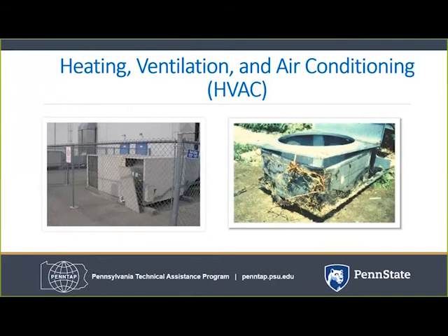There are several maintenance activities for your HVAC system that can save energy and money. First, check filters every 3 months and replace them if necessary. Tune up your HVAC equipment yearly. Look for missing or damaged panels. Check for oil leaks or drips from the refrigeration components. Clean and clear debris from equipment.